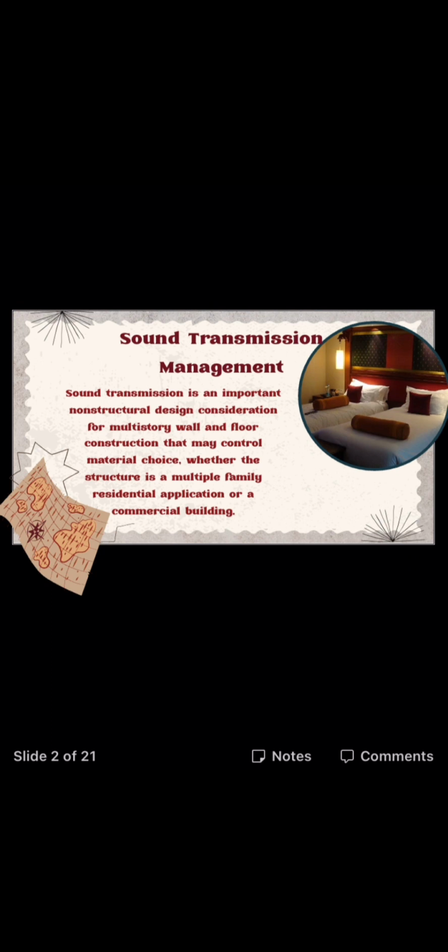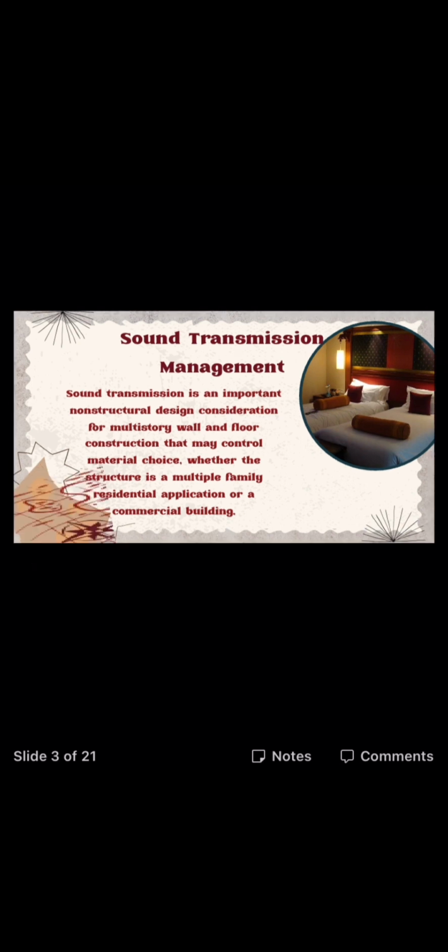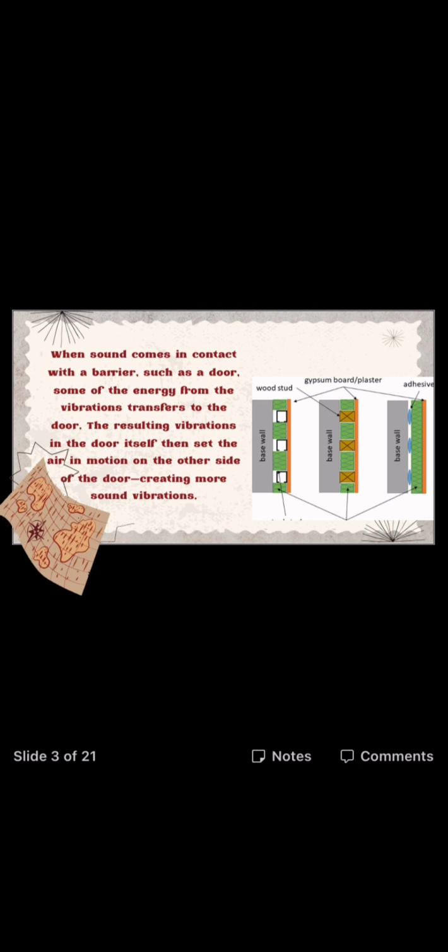Sound transmission management. Sound transmission is an important non structural design consideration for multi story wall and floor construction that may control material choice, whether the structure is a multiple family residential application or a commercial building. When sound comes in contact with a barrier such as door, some of the energy from the vibrations transfers to the door. The resulting vibrations in the door itself then set the air in motion on the other side of the door, creating more sound vibrations.